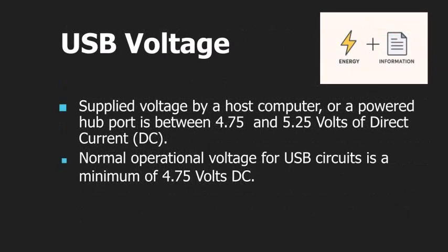Supplied voltage by a host computer or a powered hub port is between 4 3/4 and 5 1/4 volts of direct current. Normal operational voltage for USB circuits is minimum of 4 3/4 volts DC.